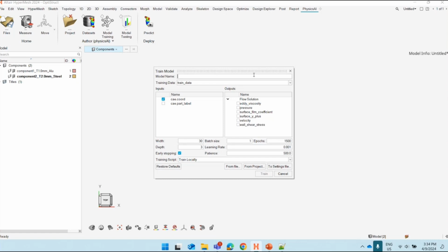Hope that is clear. So let's say you have already run 10 simulation results, but before you ran them, you didn't rename the component name. That means when you check on this later on, it has no effect. Unless you want to rerun them, then you can go and change the component name first, output the .fem or .radioss file to run again to get the H3D, and then you can use this when you're actually training the physicsAI. So far, any questions on the inputs here?